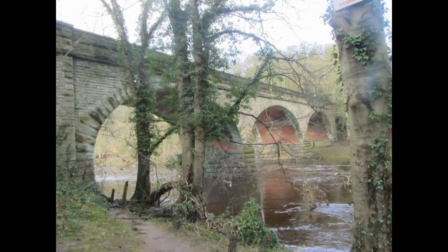Actually, the trees are particularly badly located because there's also a crack in the opposite face of the barrel, and that's because this particular bridge was subject to damage from the Boxing Day floods in 2015. And what happened was this pier settled by about 200 millimeters.